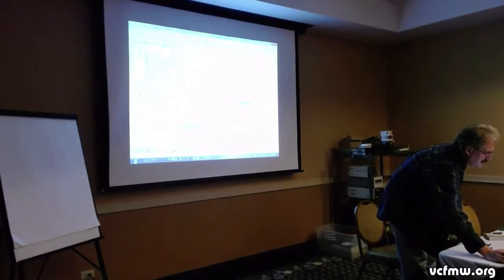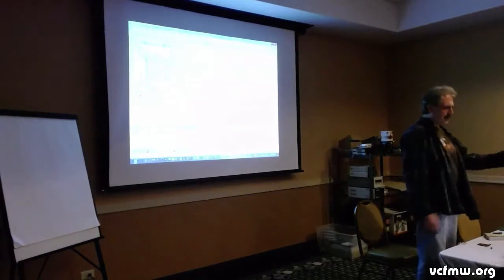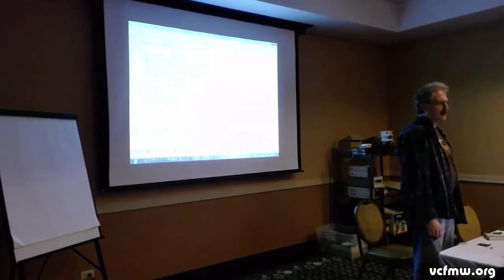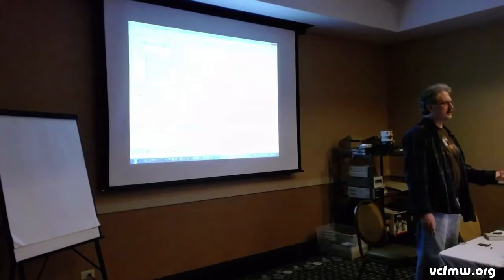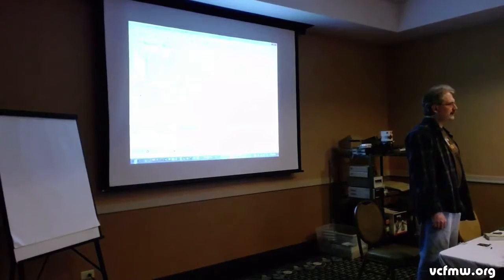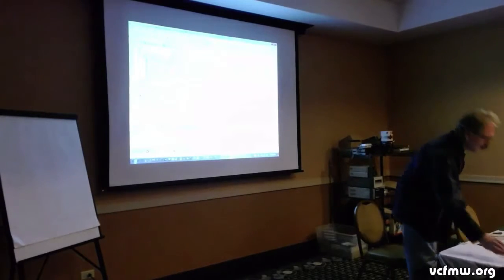And the case here is this is a cart config 2 register CE, which is basically a combinatorial definition that I defined up above. And the definition up above basically says it's right here. It says I'm going to write addresses, and the address is set to 0. The address 2 to 0 is equal to 0. And that's all there is to it there.